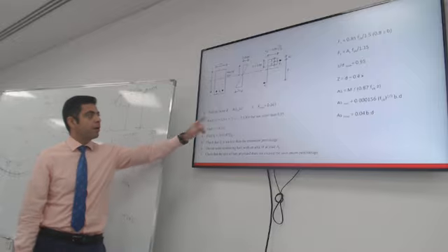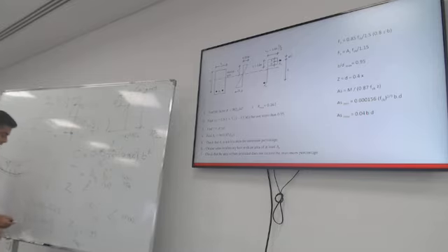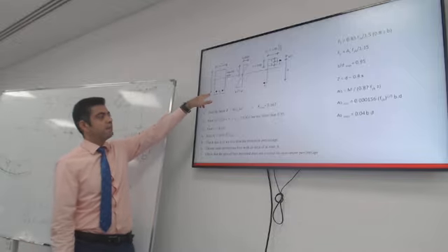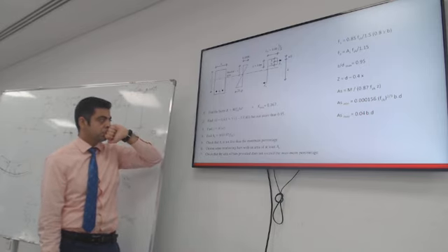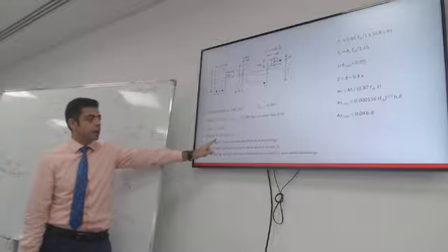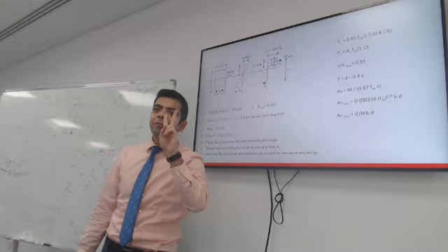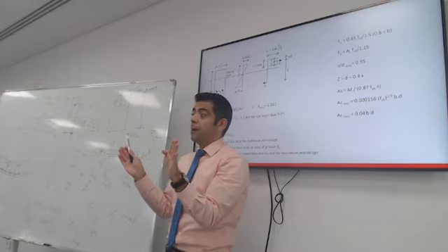Okay, from there, we will use this equation to calculate the ratio between Z and D, which is the distance between the tension and compression force relative to the depth of the section, which is the distance from the very top to the area of steel. Once we do that, we can figure out the actual area of steel required from this equation, and I need you to do two very important checks before you leave the design problem.